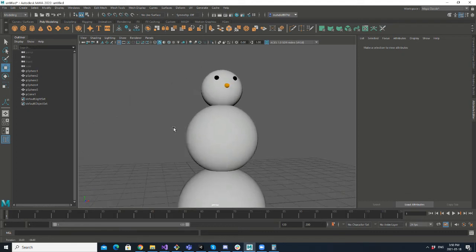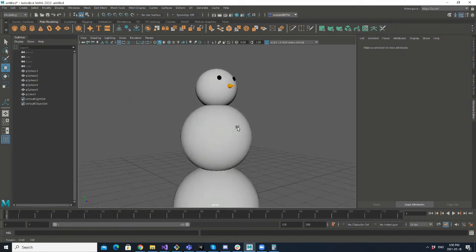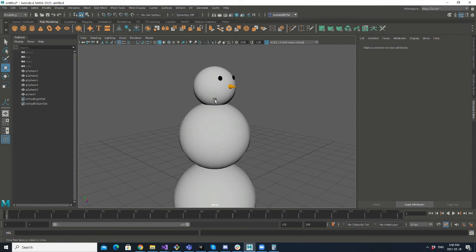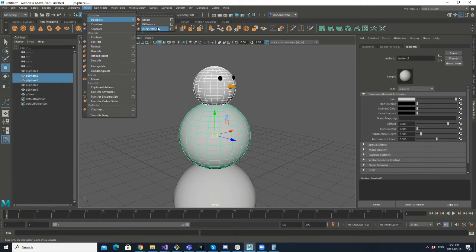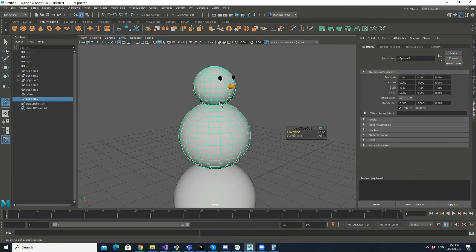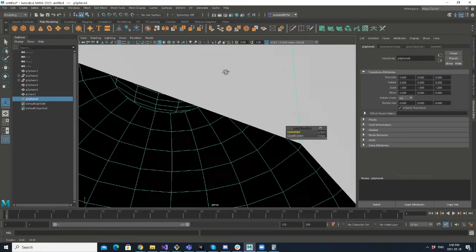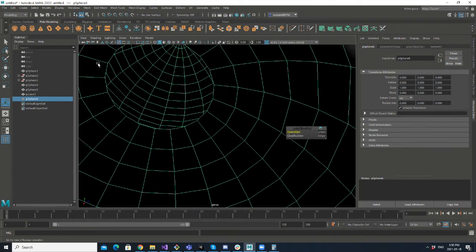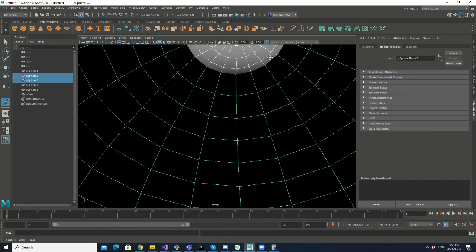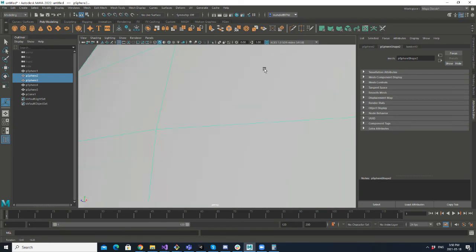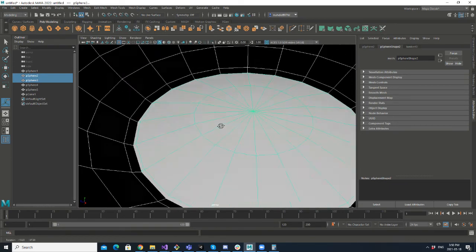I would talk a little about the collision points between these two spheres. You can obviously go, for example, to Mesh, then Booleans and Union. If I go into the objects, you can see that it just destroyed the lower and upper part of these two spheres. The bottom part is seen here, and the upper part is here.